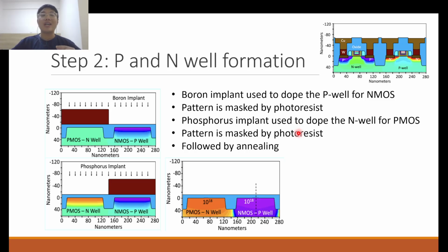So what we call implant, these are called ion implants or ion implantation. Basically what we are doing is accelerating ions at very high speeds, or at high enough speeds depending on your requirement, to penetrate into the material and occupy sites in the material, right? Occupy substitutional sites, to be more precise, in your silicon material. So that will help to achieve the doping that we want.